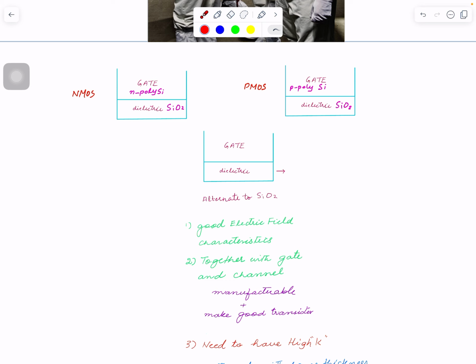See, the whole point is you bring positive charge here so that it can collect, for the NMOS case, a negative charge here. So this dielectric needs to have properties such that the atoms within it orient themselves in such a way that there is a high impact of this positive charge. So whatever dielectric we pick shouldn't be just any dielectric. It also needs to allow the strong positive charge here to affect the electrons here.